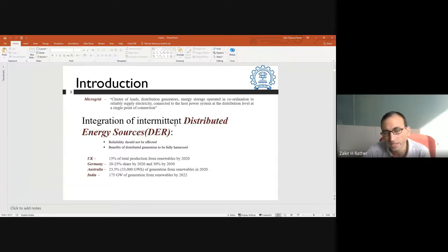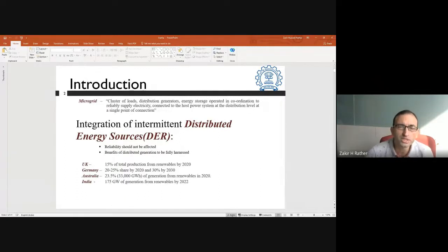Now when you have a system dominated by such sources, IBRs, then the question comes about the frequency. Frequency control of conventional systems has been well understood and well applied. The concept and the operational procedure of controlling the frequency in conventional systems has been well adopted, well accepted, and well matured. However, the paradigm shift from conventional generators to IBRs is changing the basic structure of the operation of the grid, or the operation of parallel sources in an AC system.